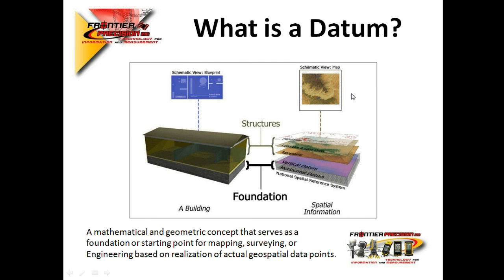Okay, so what is a datum? So if you look at this slide, and I got this from our NGS advisor here, it's a very nice little representation of trying to get an idea of what the datum really does for us when we use our GNSS equipment. You can see a definition there at the bottom, but essentially if you look at the blueprint on the left and look at the concrete foundation of that particular structure, the datum is pretty much the same thing when it comes to mapping. It is our foundation for the mapping that we do, and it's very, very important that the datum exists.